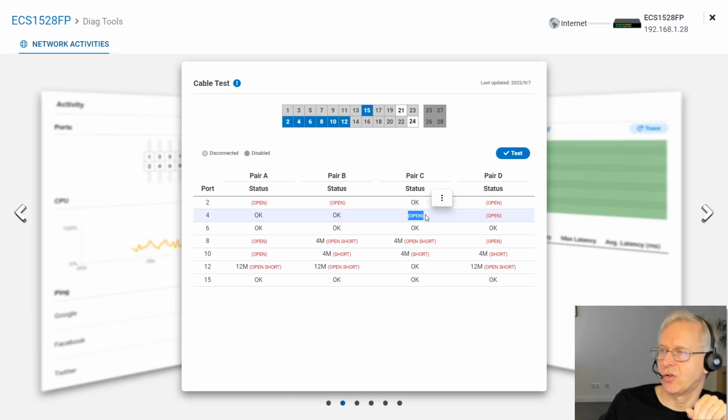then it's not connected. So what I did here with the difference, there's one cable which is a phone cable which I just pressed in. The phone cables only have two pairs, the middle ones, and actually the plug doesn't fully fit, but I just pushed it in. So it's only connecting up the middle two pairs.